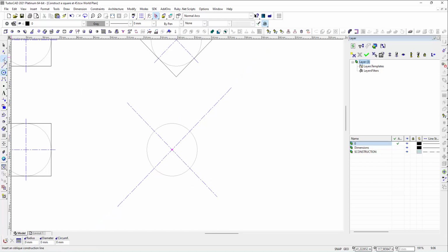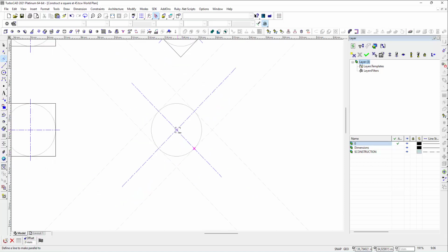And now we just again use the parallel line tool, so I'm going to select the parallel line tool to the axis. I'm going to say I to select to that. Same on this side, I, and then also to this axis we're going to go I, and to that axis there I. So now we have the layout.